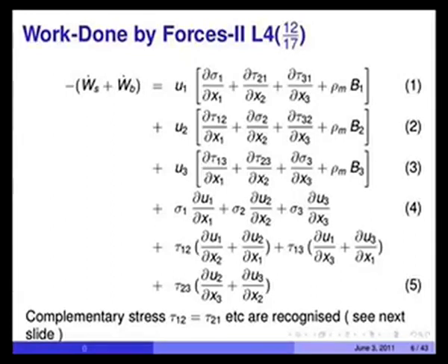If you recall, when we wrote the Navier-Stokes equations before the Newton's second law of motion, these are simply the net forces acting in direction 1, and therefore, these are nothing but the right hand sides of Newton's second law of motion. They can be replaced by the left hand side of Newton's second law of motion, and that is what I will do on the next slide. Plus, all the stresses can be replaced in terms of viscosity multiplied by strain rates. So, let us do this first.